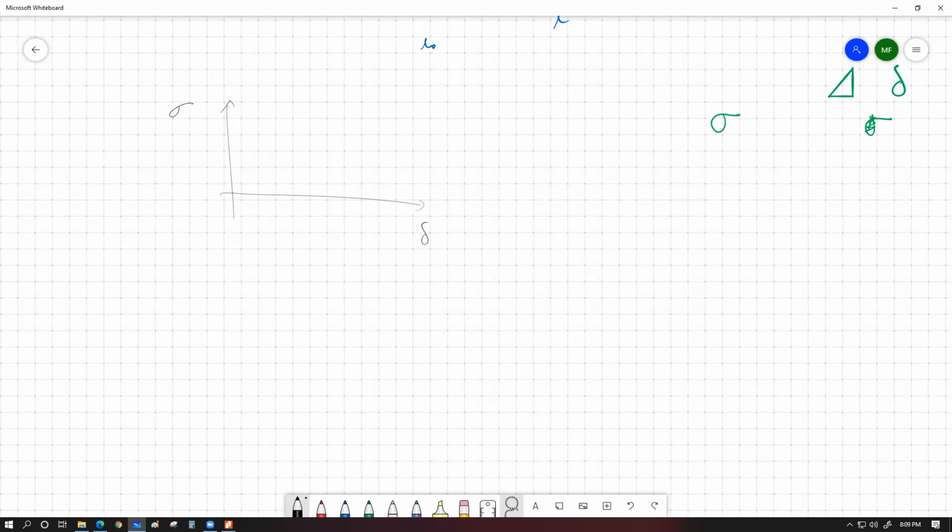So within the proportionality limit, the line is going to be a perfect straight line. When the proportionality limit is crossed, then the line is going to start to curve. So different objects can have different types of curves depending upon brittle substances, malleable substances, polymeric substances. We can have different types of curvatures. Young's modulus is the gradient of stress strain graph within the linear part of the stress strain graph. So we say that is within the limit of proportionality, that is within the straight line part of the gradient. So if we have the gradient of this much segment, that is basically what we define as Young's modulus.